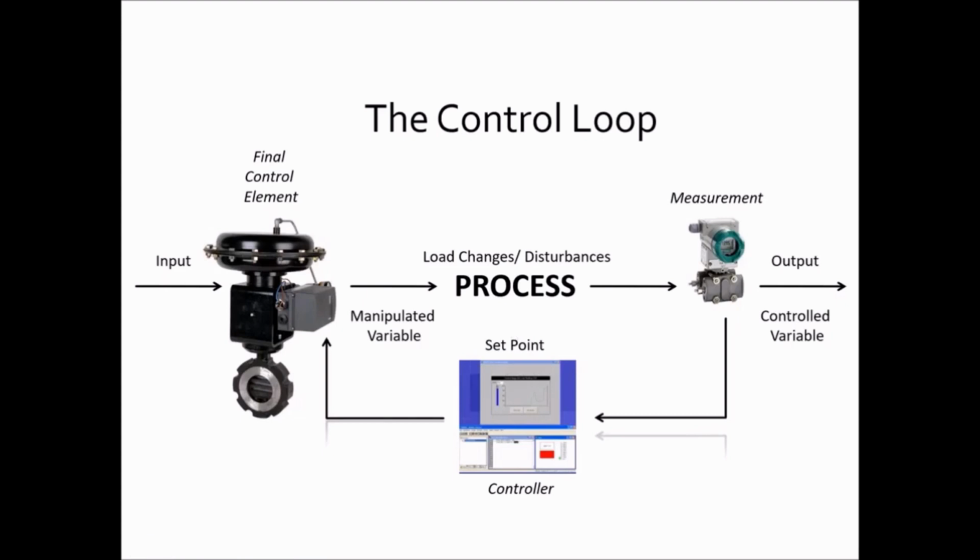So I want to make sure I pointed that out. You have control valves versus regulators, and the cost difference between them. But in regards to sizing, if our flows get so far apart that we're in that 10% to 90% range, we're looking at control valves, something that regulators probably cannot control. So it depends on the difference in pressure, certainly, and then the difference in flows.